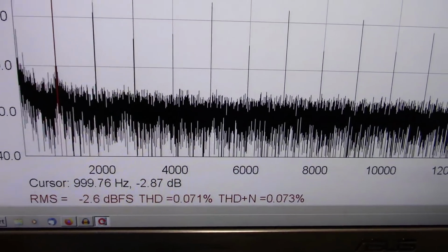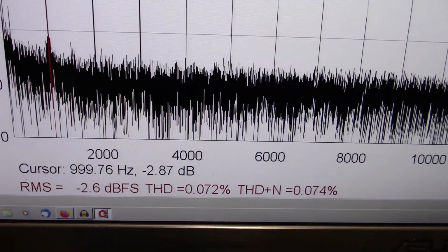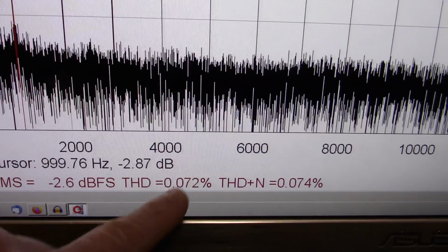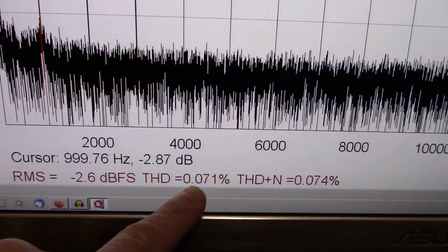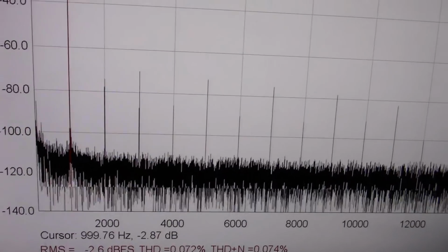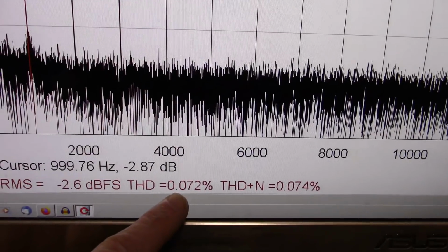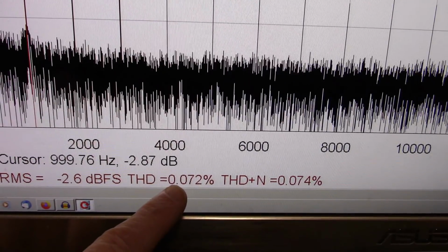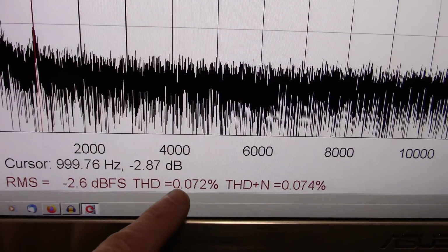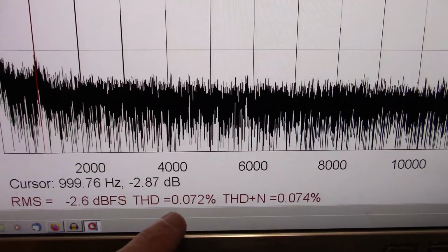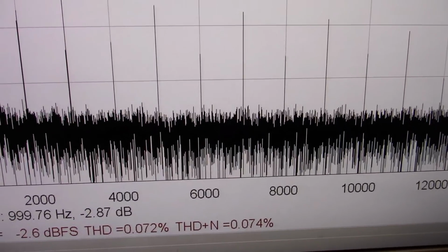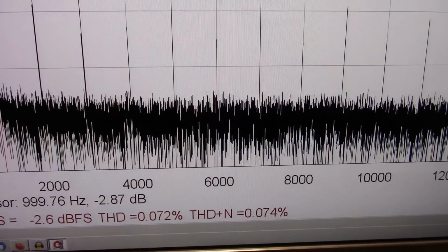I think I'm getting things back in order. But I made a discovery. This is awful. I didn't want the amp with that much distortion. I mean, we're at 50 watts into 8 ohms right now. It's about as much as my power supply can do. The power rails are maxed out at plus minus 32.